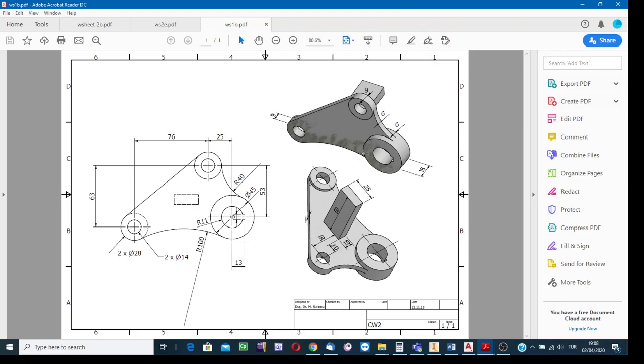While observing the object in this direction, that rectangular prism relative to the observer will be hidden. So you know the alphabet of the language: if the entity relative to the observer is hidden, then its projection is drafted using dashed lines. This dashed rectangle corresponds to the image of this rectangular prismatic extension.